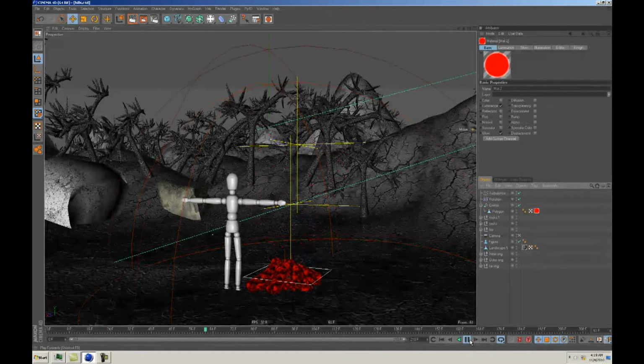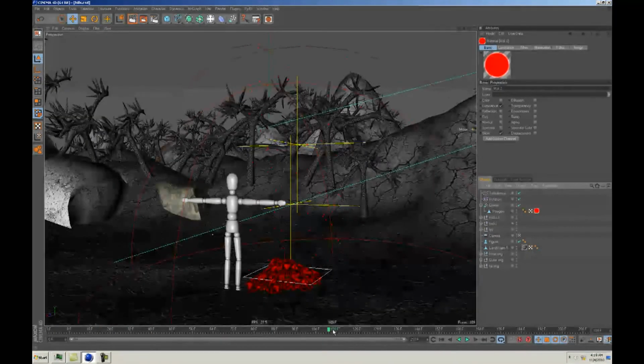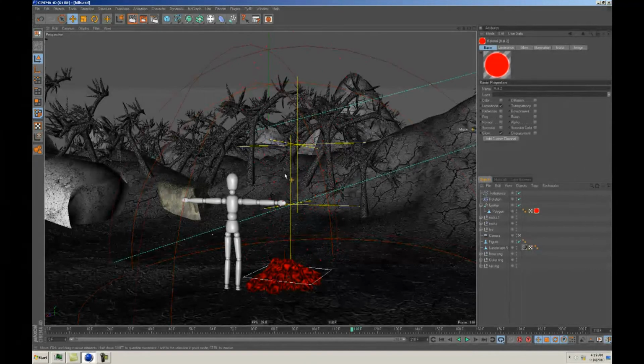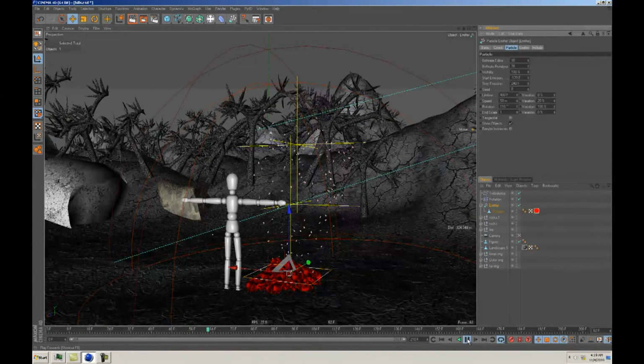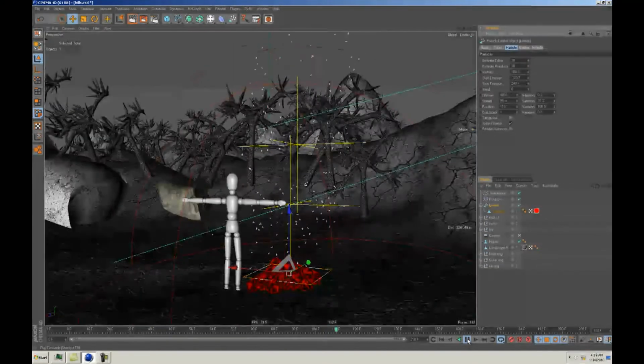But the only thing I don't like is that, as you see, they start from 0, and it takes like 113 frames or something for them to get up like this. So we don't want to have to pre-roll every shot, so that we have to wait forever for these things to come up. And if you're doing this in After Effects, there's tricks where you can pre-roll them, and you could try to go start emission minus 120, but I don't think this works. No, it doesn't.